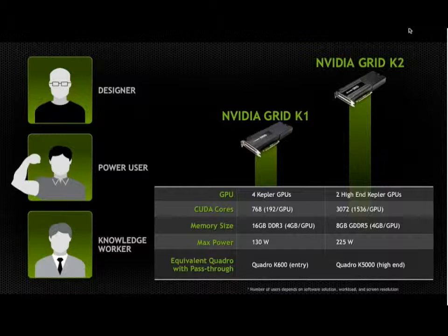These are full-length, double-wide PCIe cards. They require power. You will end up with power cables running from your power supplies to these cards. They won't run otherwise. And a pair of 750-watt redundant power supplies in the back of the server are simply not going to run the server and these cards. We hammer this because you must use a certified platform to support our cards.